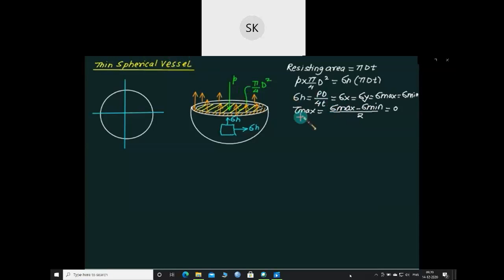And if we draw the Mohr circle of this one, the Mohr circle will be a point. That is the same value for x, the same value for y. So the Mohr circle has radius equal to 0. And it clearly indicates tau xy equal to 0. And if we draw the 3 Mohr circles, then one Mohr circle is drawn, the other 2 Mohr circles will overlap, and then this radius will be equal to tau max.